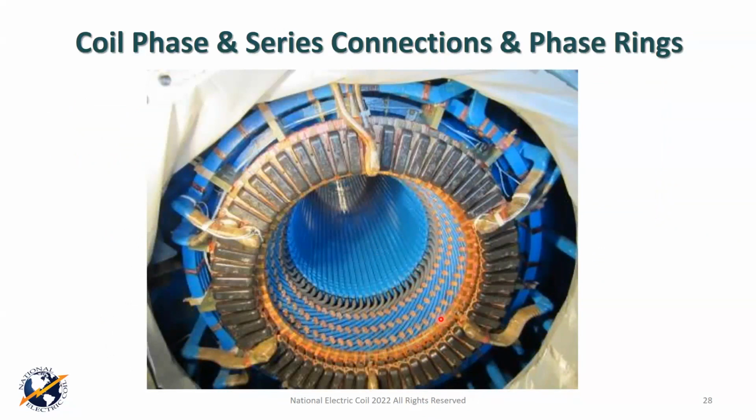There's an inner surge support that you see right there that's also laced in. So that's quite good. That's really a nice thing. Then we got all these series connections that are all clipped and capped. And then you got blocks in between those, just like we saw there. So that's pretty cool in the way that's established. And then we got the phase connections that come up here to the phase rings that go along. You have the phase connections at the different places, okay?